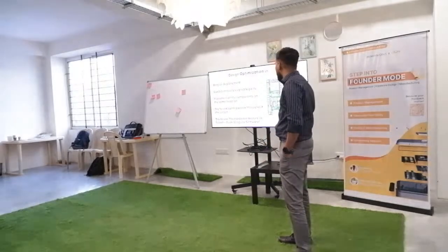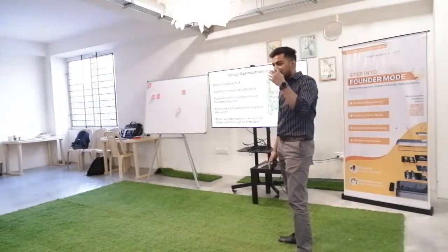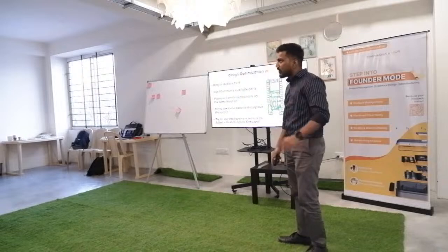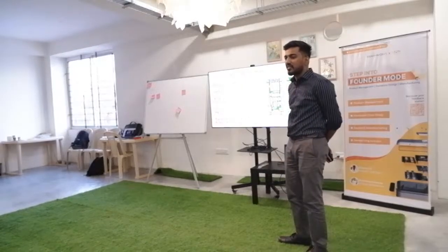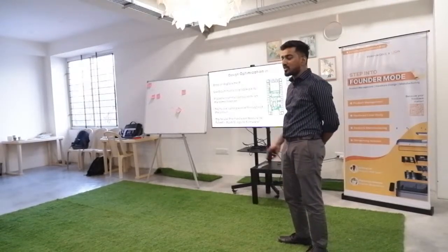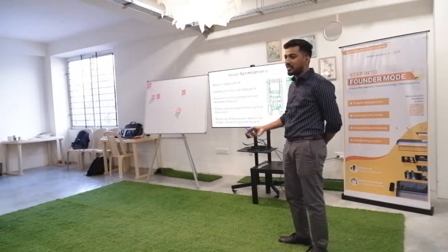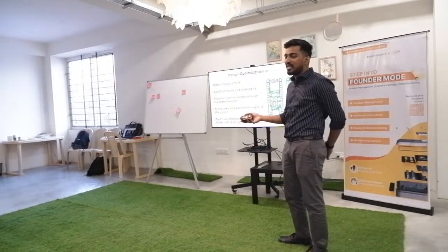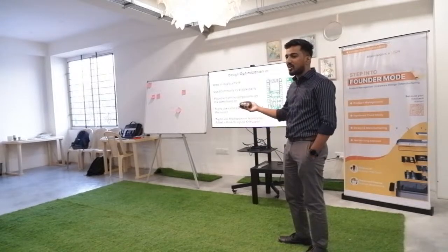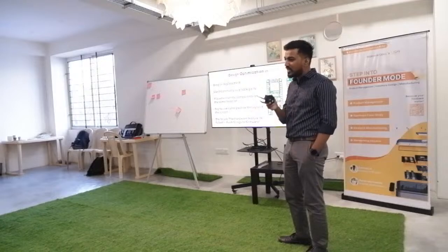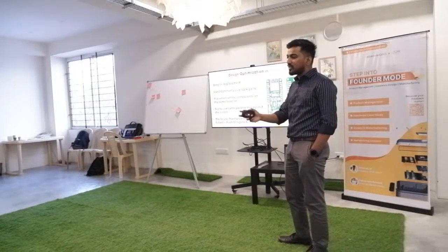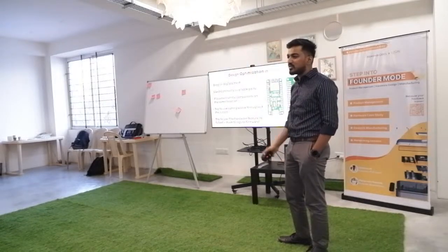That is what happened for us also. We have the 5.1K resistors, so when we were making 3,000 units, we had to procure 21,000. So the cost was extremely low because you're getting 21,000 of those. But if I use a 10K, I have to make a separate lot, and for 3,000 units the cost will be higher. So between 3,000 and 21,000, it makes a huge difference.